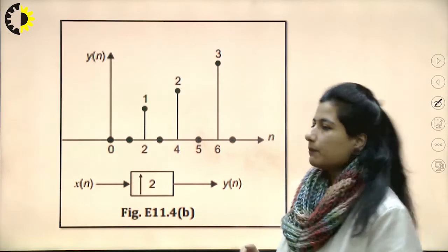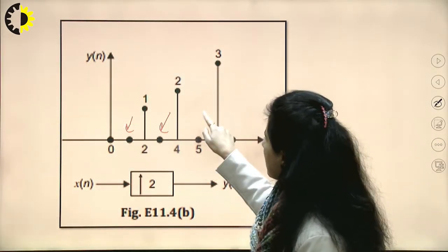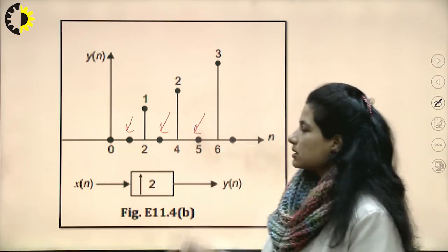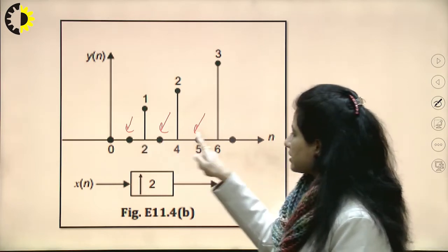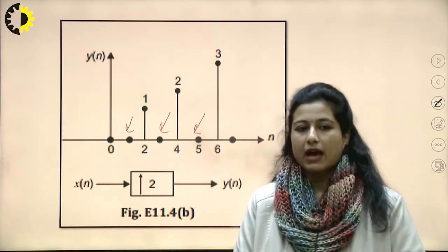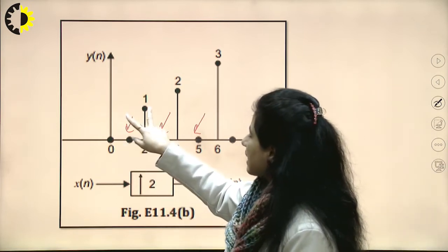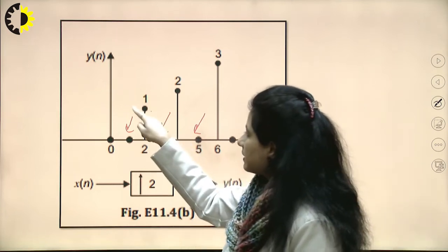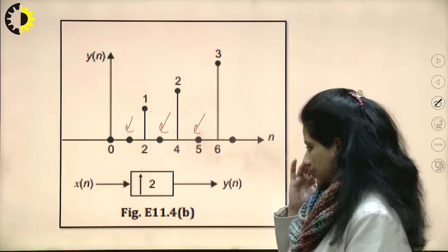So how would the complete signal look? These are the interpolated zeros between every two samples. This is how we implement the interpolation. But actually these positions do not have the value 0. We have to approximate these values by predicting from the previous sample and the next sample. It would certainly have some value which would help me in generating or reconstructing the signal.